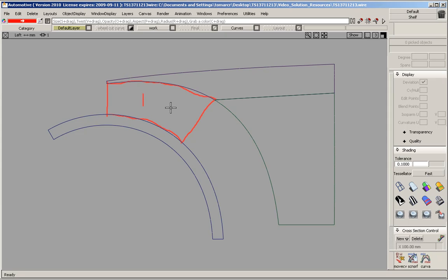So what we're trying to create is the bigger surfaces first. Our second one will run this way. So that's surface 2. Our third one, I'm going to detach the surface over here. Then what I'll do is extend this feature line and we'll create a surface in here. I'll show you how to do that.